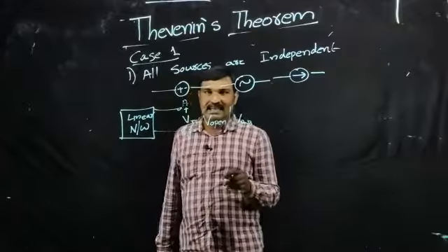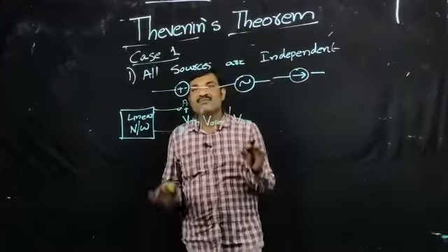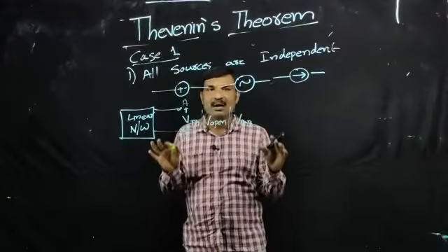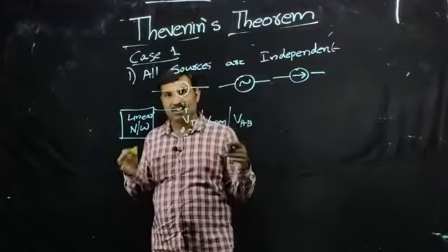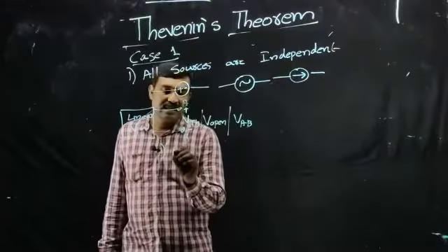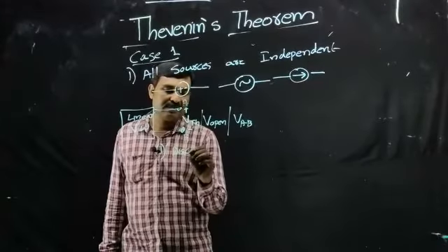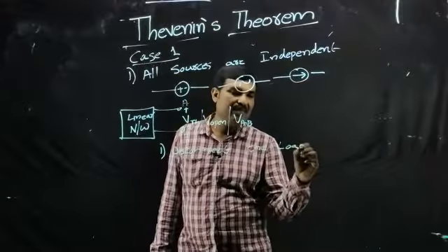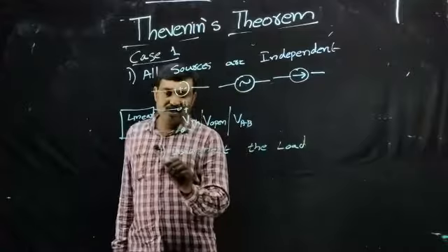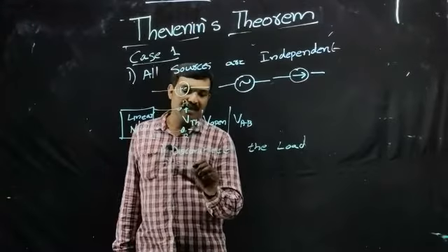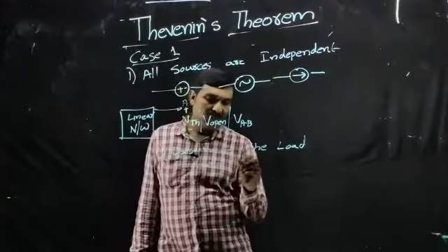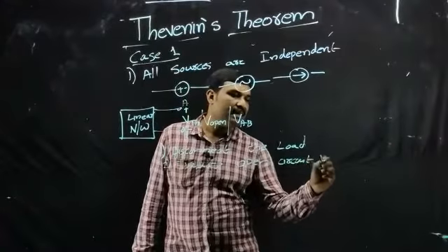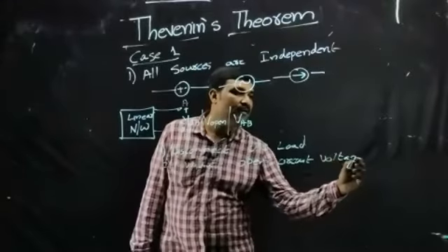For evaluating VTH, what we have to do is first disconnect the load, right? And determine the voltage across the open circuit load. So disconnect the load. Then evaluate the open circuit voltage across the load, right?